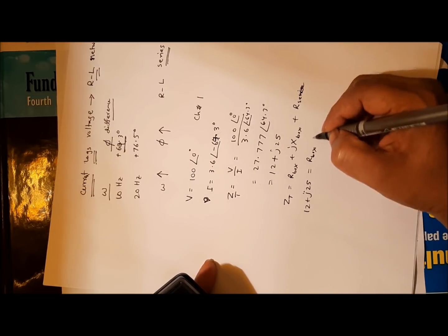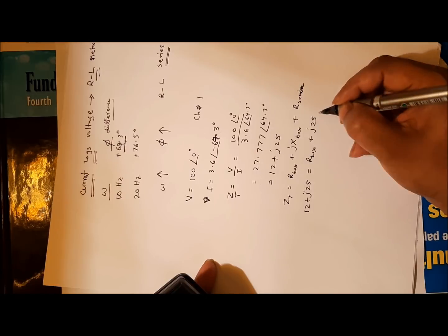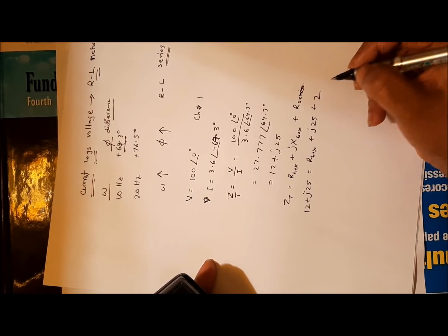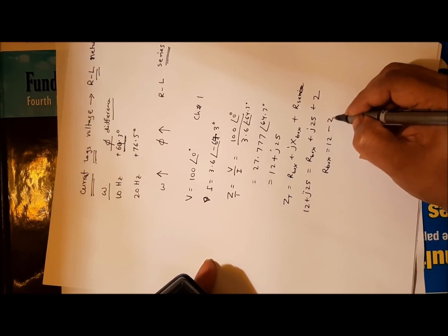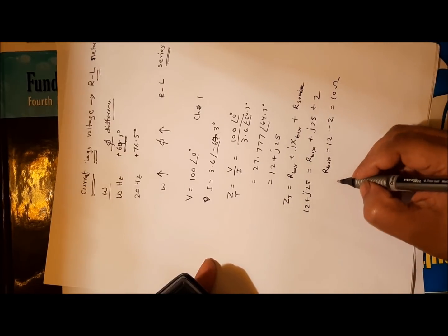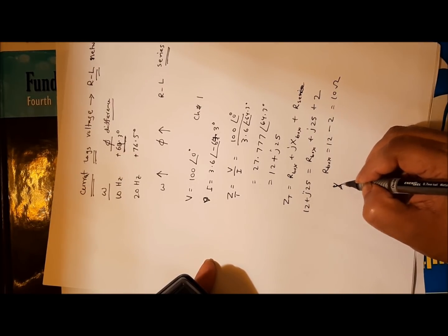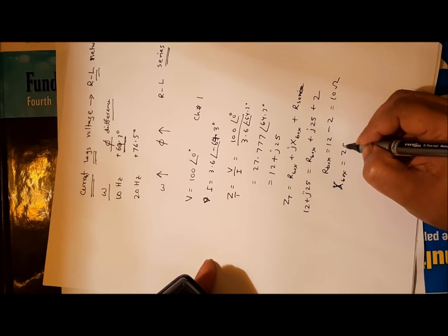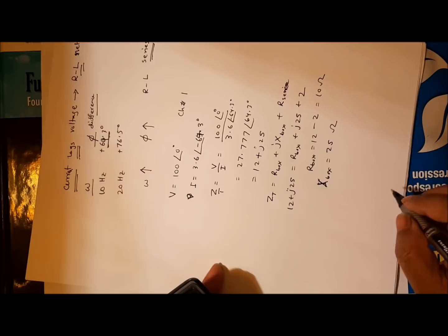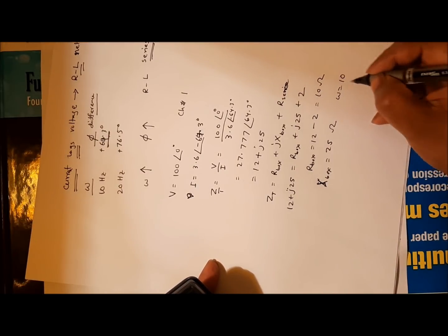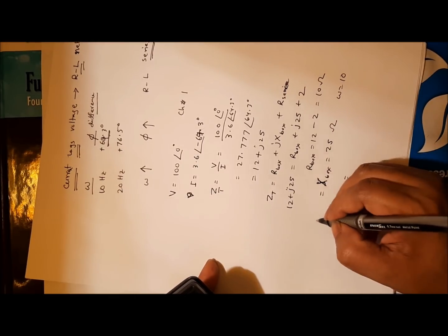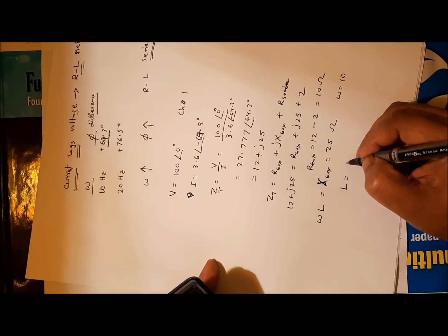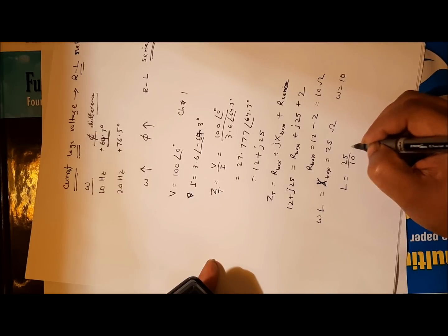So R box plus jX box, where X box is 25, and R sense equal to 2. You see that the resistance of the box will be 12 minus 2, so 10 ohms, and the reactance of the box is equal to 25 ohms. We solved it for omega equal to 10. X is equal to omega L, so L will be X over omega, 25 over 10,